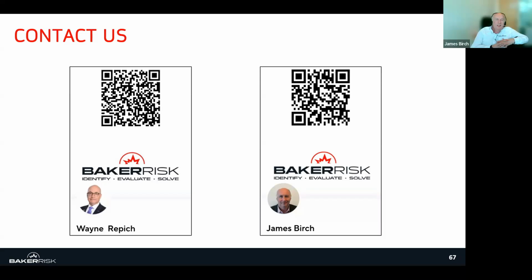In my experience, I would be looking for something where you are probably talking between 10 and about 20% of the tag items having a safety critical function. It varies. It depends upon the process. It depends on how many major accident hazard scenarios you have for a plant. But it often seems to come out as a reflection of the 80-20 rule. Rather, 80% of your safety benefit is coming from 20% of your equipment.